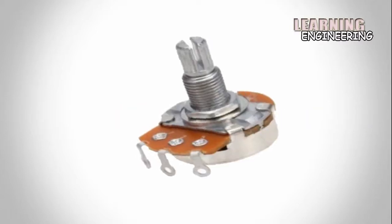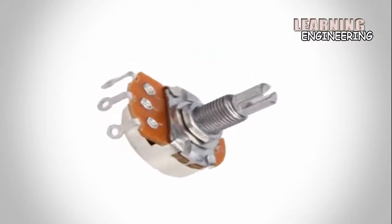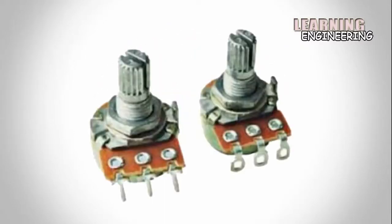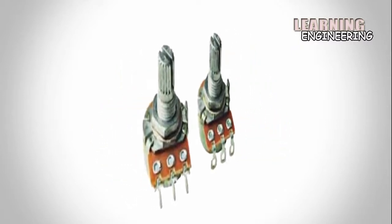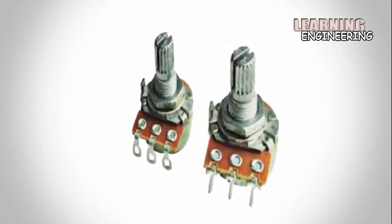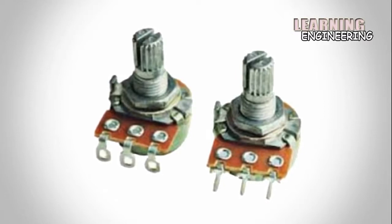Potentiometers. A potentiometer is a 3-terminal device which is used for controlling the level of voltage in the circuit. The resistance between two external terminals is constant while the third terminal is connected with a moving contact wiper which is variable. The value of resistance can be changed by rotating the wiper which is connected to the control shaft.